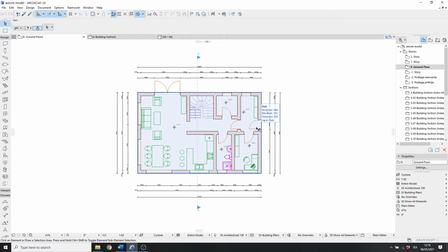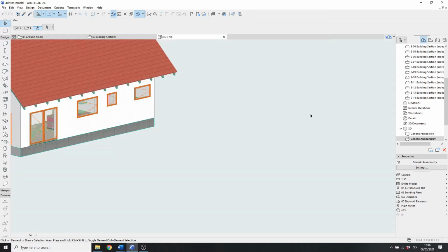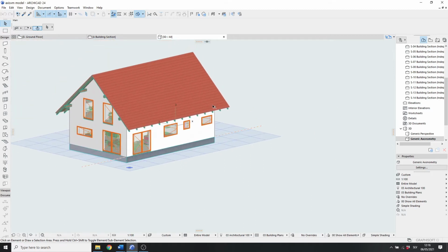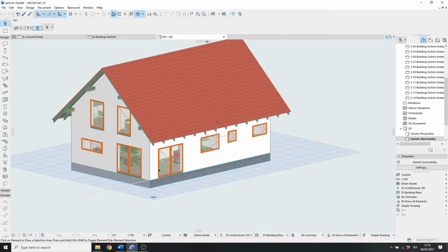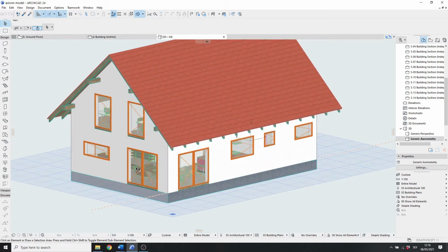The software that we will be using for architectural modeling is ArchiCAD, while our structural analysis software is AxisVM. Now, if we look in front of us, we have a 3D model that is something that we usually receive from an architect. It consists of many structural elements, like walls, beams, slabs, etc. But it also has a lot of elements that are not necessary for structural analysis, like windows, roofs, furniture. Our task prior to exporting to structural analysis format is to determine which of these elements are structural and assign their structural parameters.